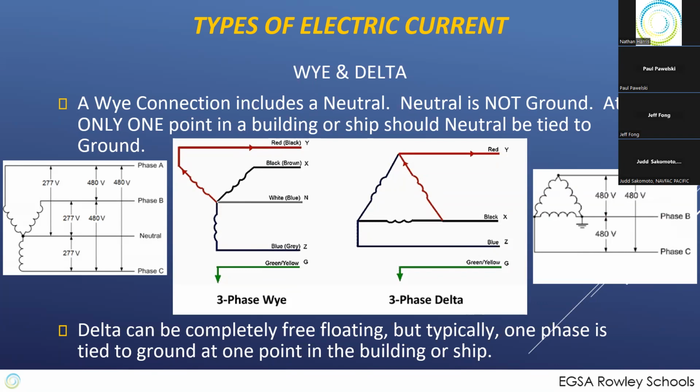So the first thing we want to bring up on safety is if you're working on live equipment, assume that even the case is energized until you can confirm that there is no potential difference between that frame that you're about to touch and the ground connection for that piece of equipment. And until someone's checked that that ground connection is matching the central ground connection, assume that it is hot.